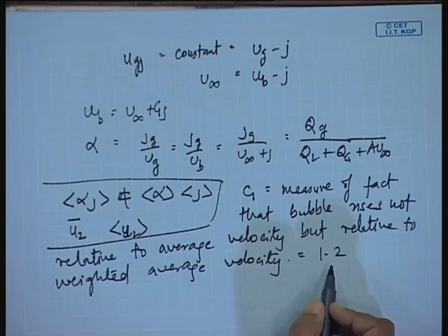Normally superficial velocity and volumetric flux have the same mathematical expression, but their meanings are completely different, and if we really refer to a 3-dimensional vectorial form, then they would have different physical interpretations. Both of them are volumetric flow rate divided by the total cross sectional area, but the definitions are completely different. One means the volume flow rate per unit cross sectional area, and the other is the velocity which that phase would have if it had flowed alone in the pipe. Accidentally, for 1-dimensional flows, both of them take the same mathematical expression.